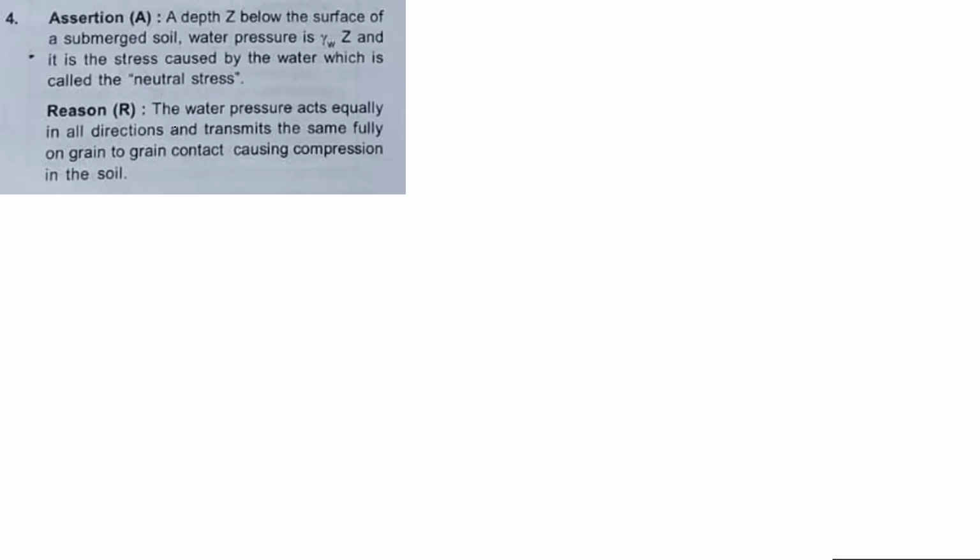Okay. The next statement: the water pressure acts equally in all directions. Yes, up to this is correct. And it transmits the same fully on grain to grain contact, causing compression in the soil. No, this statement is incorrect.